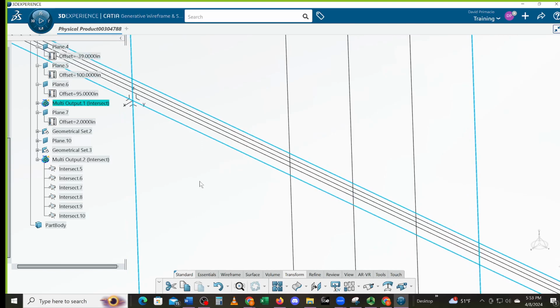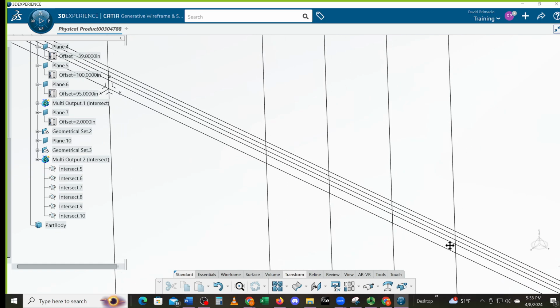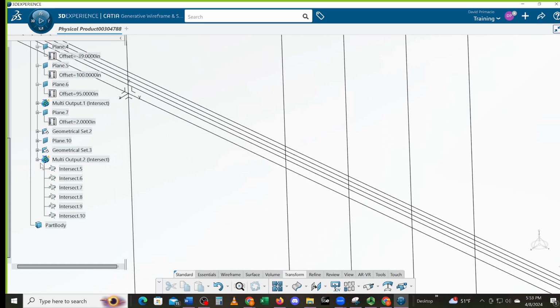Well, I think what screwed it up was because these are all individual lines. What screwed it up is that when I trimmed it, it made them all one. When I do a trim, it doesn't just trim lines like you think it would. It makes that square one entity. So if you click on output to intersect, are there any lines that are overlapping? Okay. So I did all those for my steps.